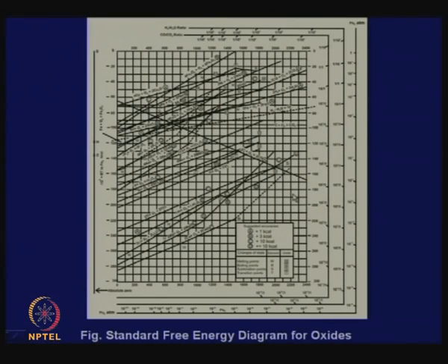So, now we have understood the Ellingham diagrams. The importance of this line we must understand now. This line shows that as the temperature increases, carbon monoxide becomes increasingly stable, because free energies of formation of carbon monoxide becomes more and more negative.